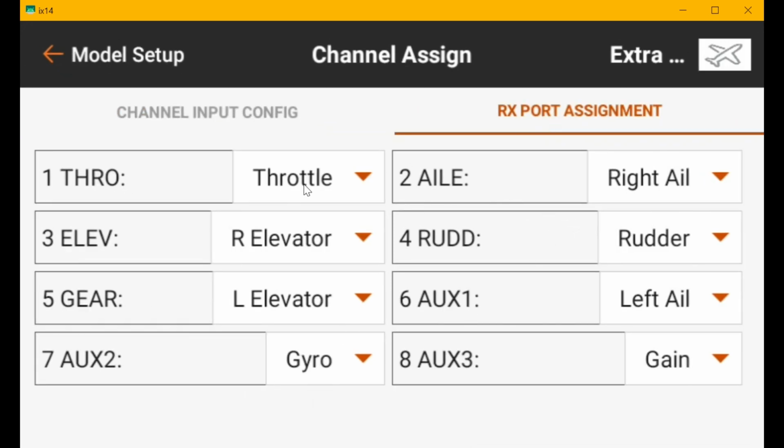So anyway, you can do dual ailerons and dual elevators, rudder and throttle with a 6-channel receiver. And of course, the AS3X safe receivers can actually hear channel 7 through 20 on a 6-channel, and 9 through 20 on an 8-channel, and 11 through 20 on a 10-channel 360 receiver.